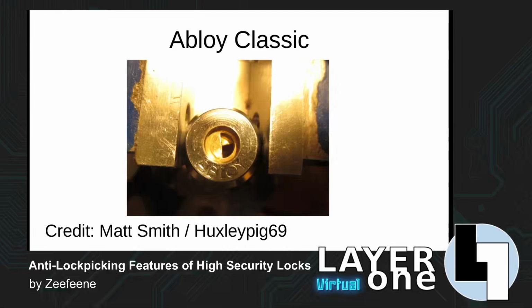but in terms of the possible configurations of discs, a minimum movement disc does not move at all, and a maximum movement disc has to move 90 degrees. And it turns out it's incredibly difficult to design a pick that is both capable of turning one of these discs 90 degrees, and yet is small enough to fit through the remaining gap if you find yourself unfortunate enough to be faced with a maximum and a minimum cut disc right next to each other inside the lock mechanism. Huxley Pig has written a paper on this where he goes into much more detail on exactly how this works. I highly recommend reading it if you can find a copy.